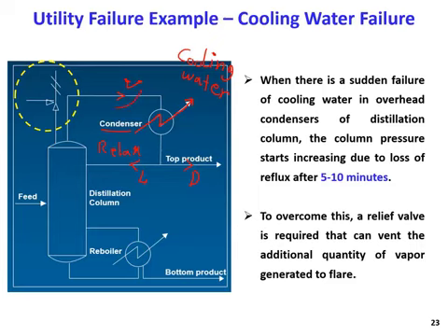The vapor here will accumulate. We cannot condense this vapor and create liquid. So either it will accumulate in the column, or it will be recirculated to the column as a vapor. So it's a malfunction. We cannot liquefy the vapor, so it accumulates. Once the vapor accumulates, the pressure inside the tank will increase. So we need to design a pressure relief valve to purge the vapor in the distillation column.